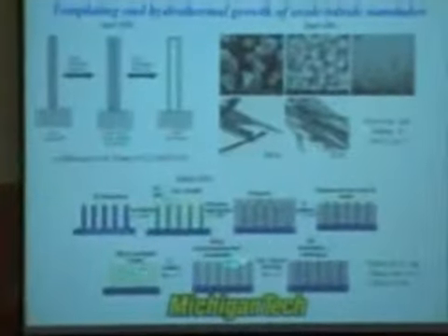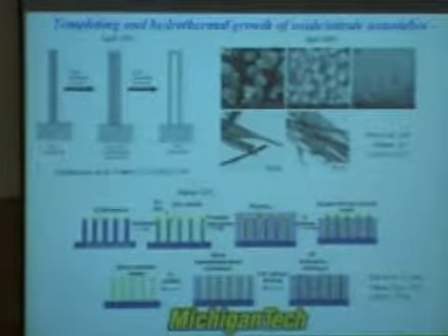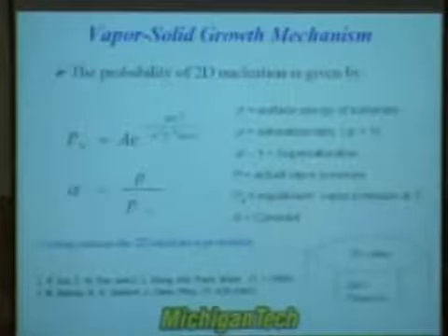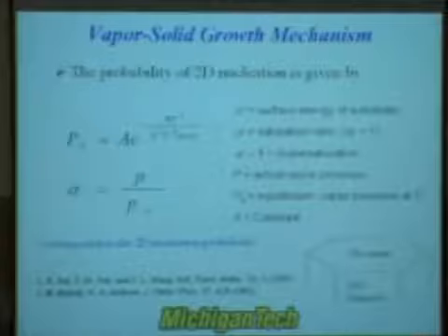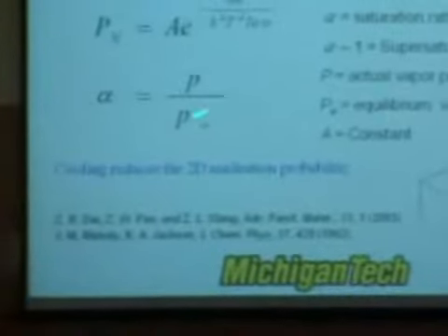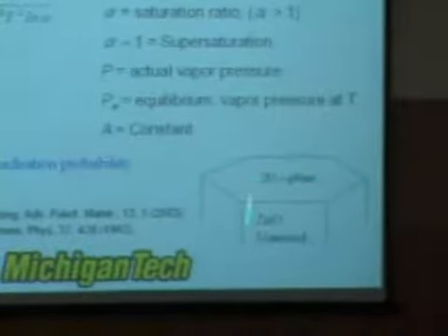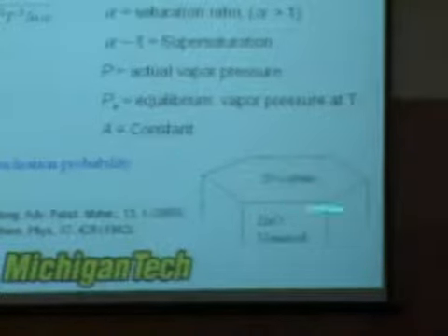Wow, this is a very complicated process to make all these zinc oxide or nitride nanotubes. But we came up with a much better way. We looked back to the theory. Let me skip some of them here. We found that if you can cool your growth conditions so that you avoid the diffusion of the growth species on the zinc oxide nanorod, which is a hexagonal shape here.